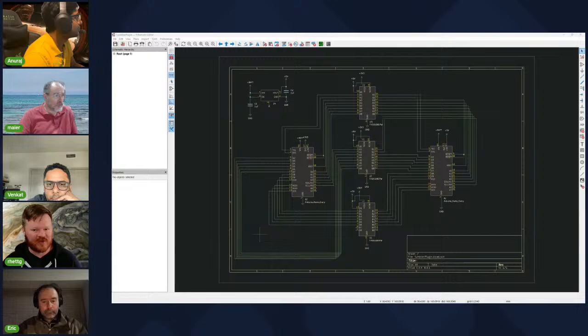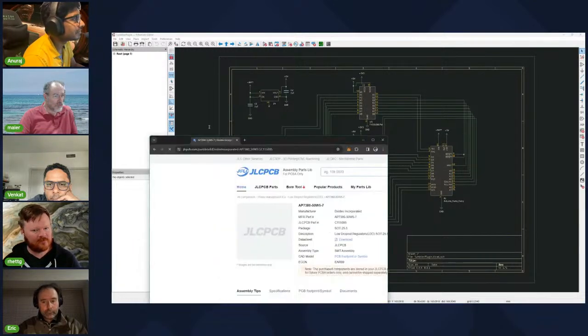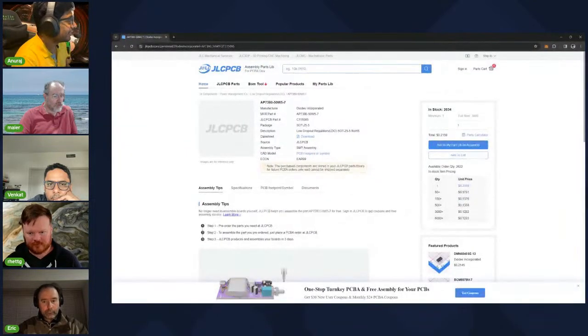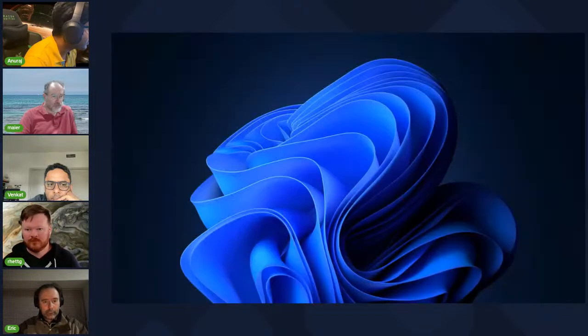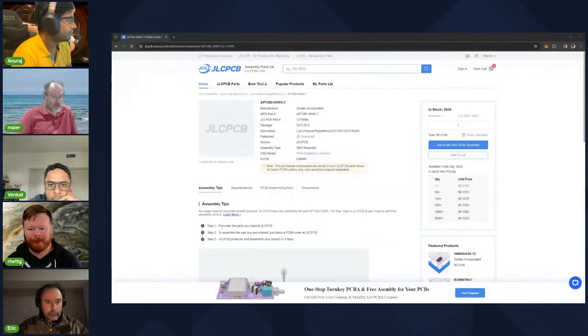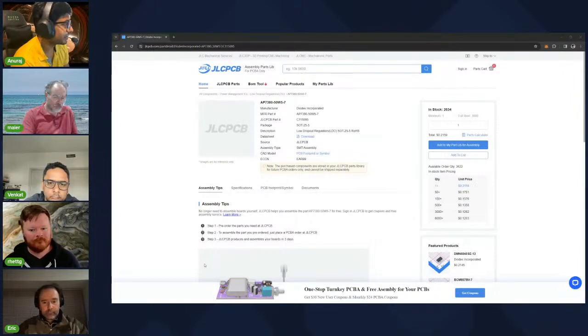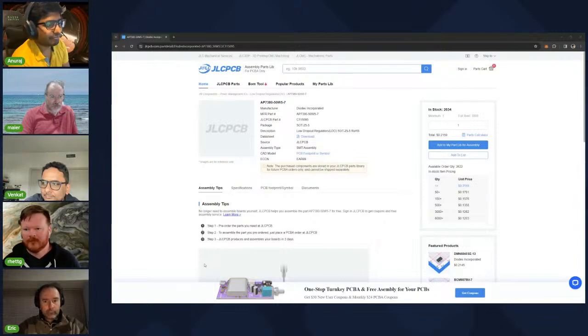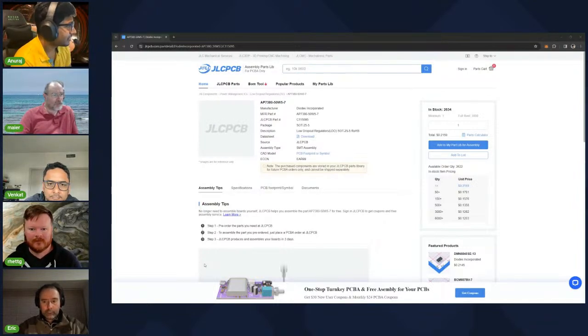And then you could presumably just get the PCB and add components yourself. Yes, but I didn't want to solder surface mount components. If the components are really small, it's a problem. And I didn't have a surface mount soldering iron or a hot air iron, where you blow hot air through it and it surface mounts. I could have done that, but I wanted to try out the manufacturing part itself, so I wanted to learn how to manufacture PCBs remotely.